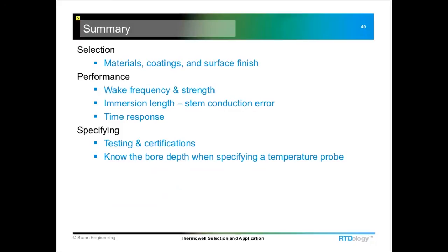So I guess the most important things that I want you to walk away with today is, make sure we select the right materials, coatings, and the surface finish for the Thermowell. Do the wake frequency and strength calculations if there's any doubt about whether it's going to be strong enough.